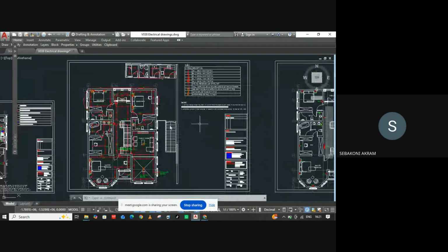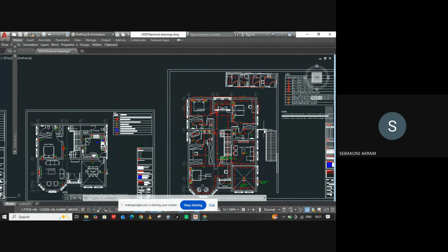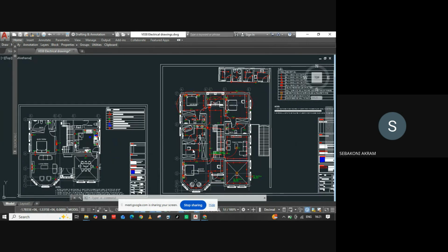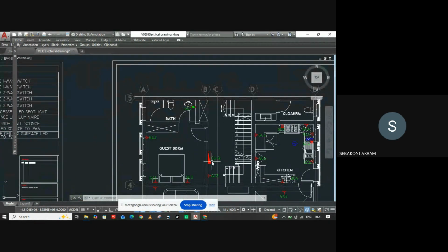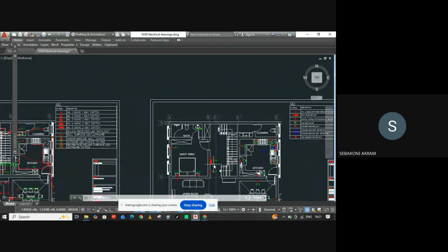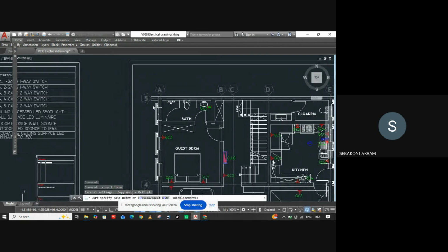My purpose of bringing that was a way of learning how to interpret drawings, to be cautious of background and lower ground. So you can maybe research more about that. But back to the electrical, I was explaining the grids. You can see we had positioned our CU here on lower ground. At that position, you can copy it here, because there's a CU exactly above it, so that the cable just runs straight up to supply the other floor up. So you can copy it like that.